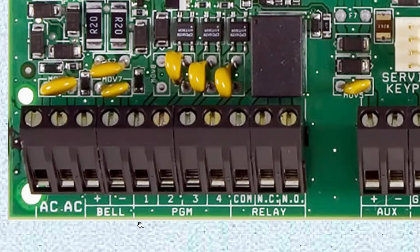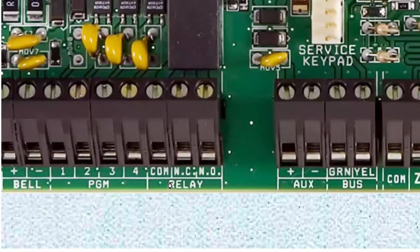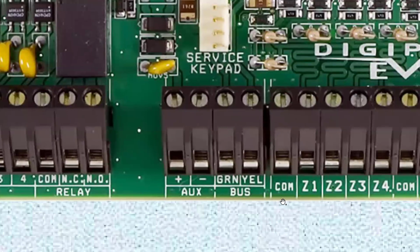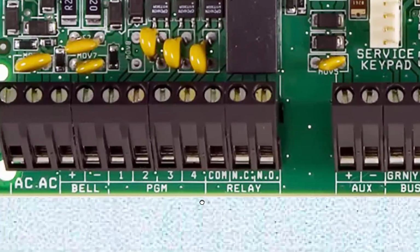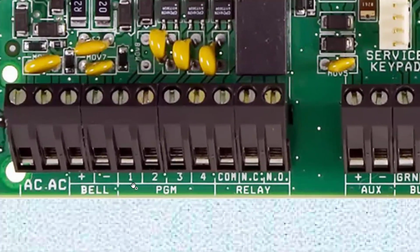All right. Now here we have program and relay contacts, and here's a common. These commons are the same point. Here's a common as well. It's like a ground reference for the sensing circuitry and whatnot. 1, 2, 3, and 4. This particular board has 4 program terminals, and if you are going to install these systems, you should familiarize yourself with them. So there's going to be some reading and maybe watching some videos presented by the company who sells that, or maybe participating in some live training.